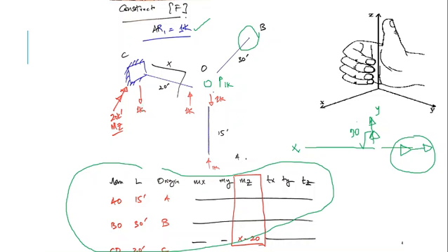Okay, I have balanced it as well, 1 kip with downward 1 kip. Now this load is in Y direction and this member is in X direction. So the loading is in Y, the member is in X. So there would be a moment in Z direction. Moving this load towards this support, it forms an anti-clockwise moment. So I'll have to resist it using a clockwise moment. So this is a clockwise moment in MZ.